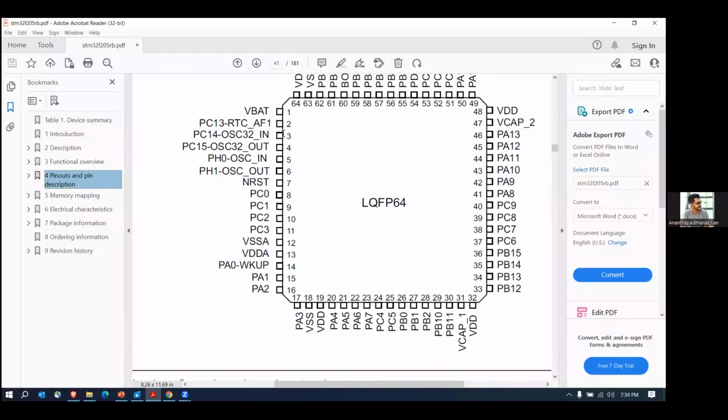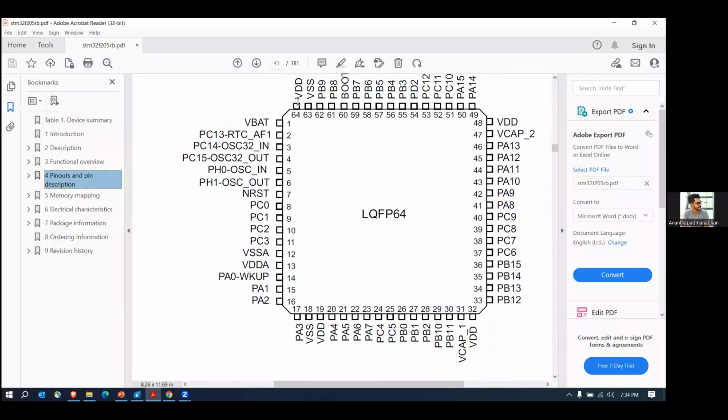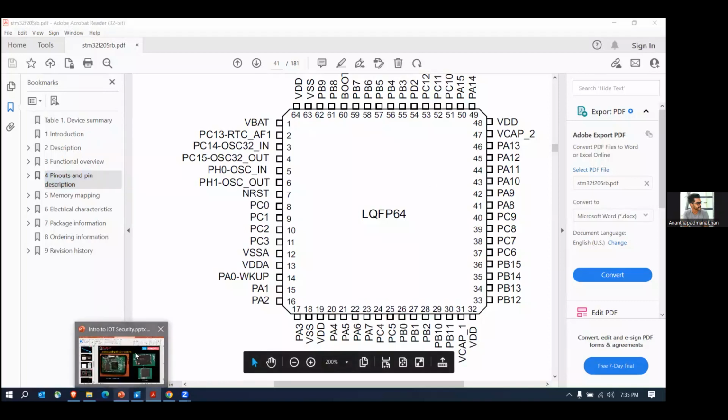Each of those pins stands for something particular, either ground or voltage, and if it is using a UART protocol, it will have a receiver or transmitter pin. We can find all those things using the data sheet. Once you find out which is ground and so on, you can mark it, like pin number 64 is the ground, 63 stands for voltage, and so on. From this you will get an understanding of what kind of pins are used in that device.